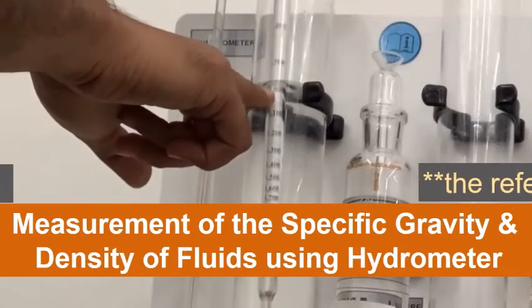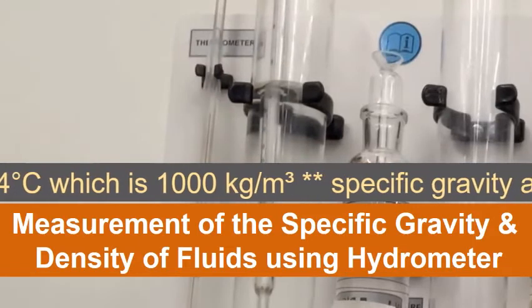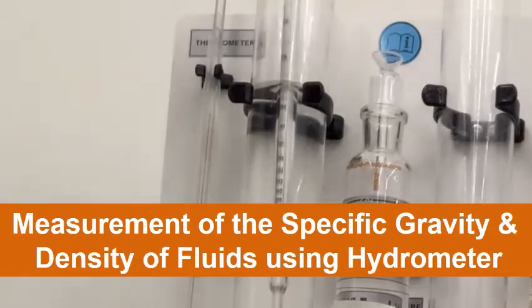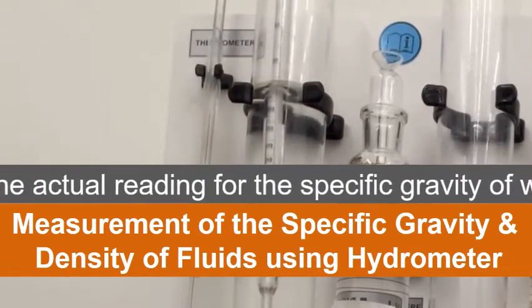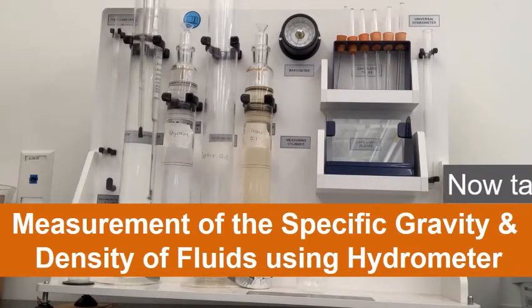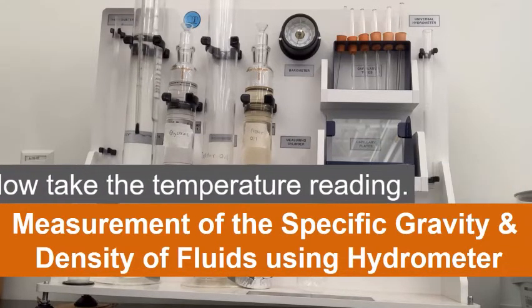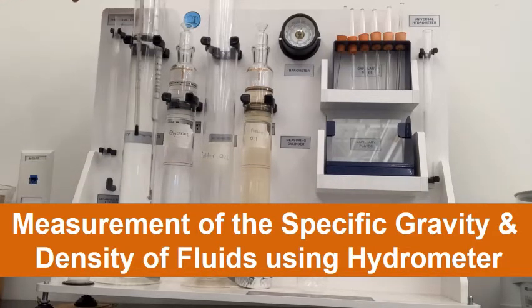So if our water is at 4 degrees Celsius, our reading must be 1 for the specific gravity. But since our water is not 4 degrees Celsius, there's a slight difference, but it's almost 1. So if we take the temperature, the temperature here says it's 25 degrees Celsius. So the specific gravity is almost 1.